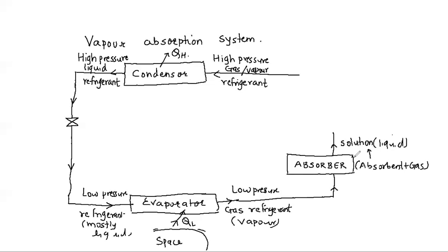Okay. This liquid solution would then enter the solution pump. It would then enter what is called a liquid pump, a solution pump. Okay. And as a result, the pressure would increase. So this was the low pressure solution, and because it is now pumped, what you are expecting is a high pressure solution.